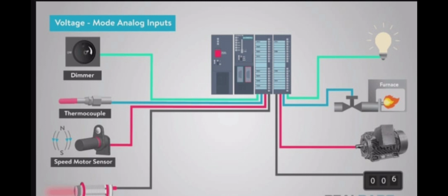Now let's move towards the analog input summary. So what you have understood is that analog signals are the fundamental pieces of information upon which the control system operates to determine further derived information or control parameters according to which the plant can best be operated. It means it takes the information in the form of 4 to 20 milliampere signals from the field devices as sensors and gives it to the analog input cards.